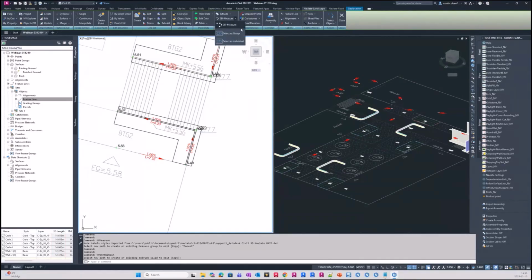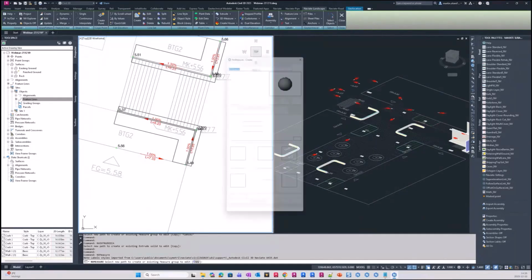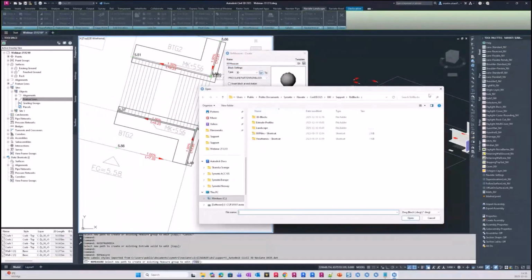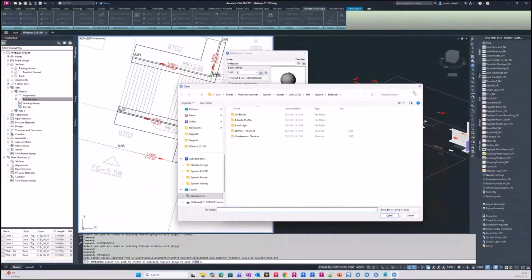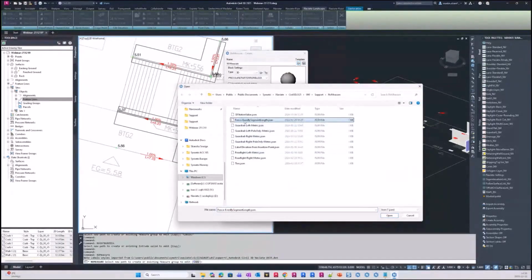Also with this 3D measure or objects along line, you can also save your templates or import templates. Like if I pick this feature line, I can import a sample template here. Oh, this one. So I got this fence even by segment, for example.